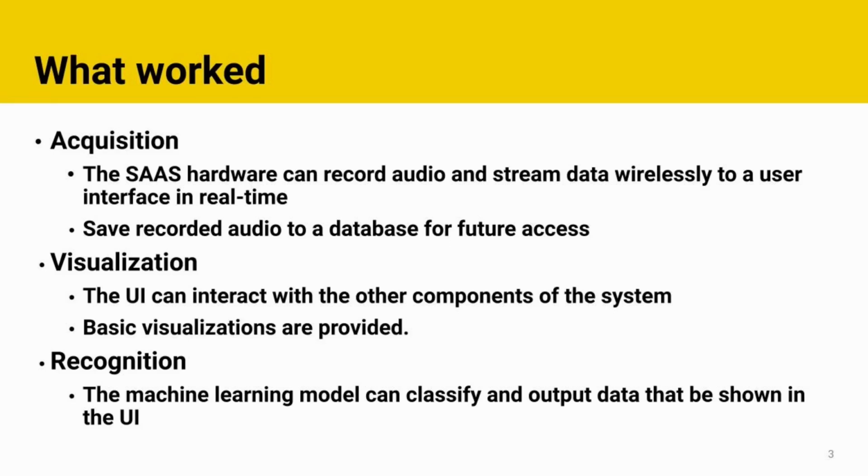In terms of SAS hardware and data acquisition, the main part that we were able to integrate effectively was the data communications. The first main part that this can be seen in is the data streaming. Getting the Latte Panda to efficiently collect serial data from the Arduino and send it to the UI in real time was a bit of a task. But we were able to use multiprocessing and WebSockets to approach this problem and allow the client running on the Latte Panda to communicate with both the Arduino and the UI concurrently.